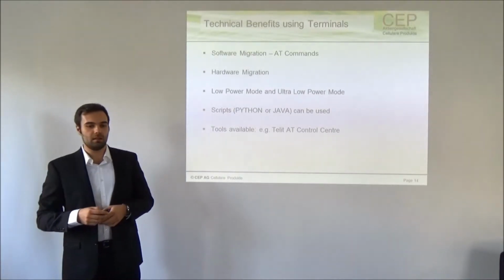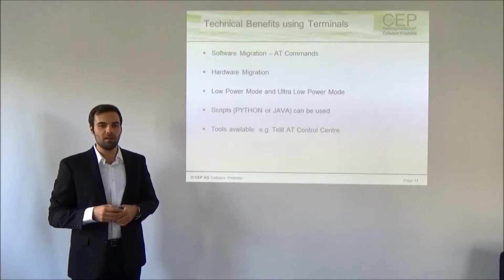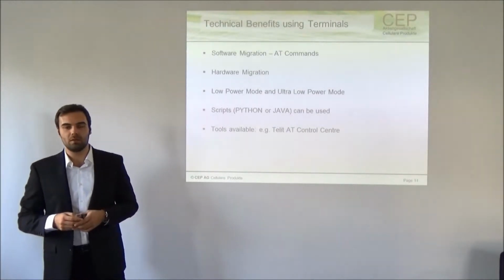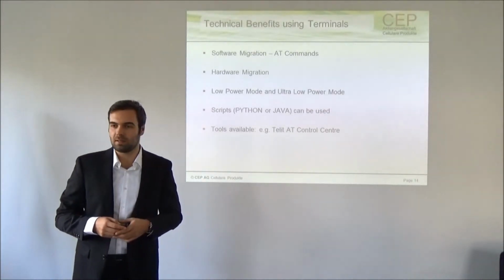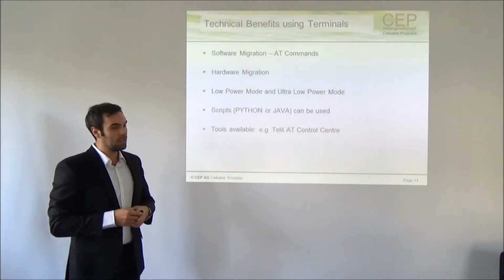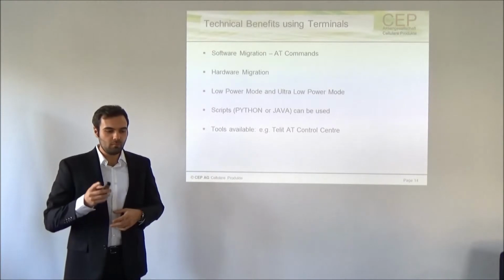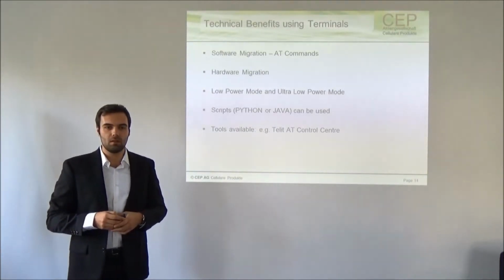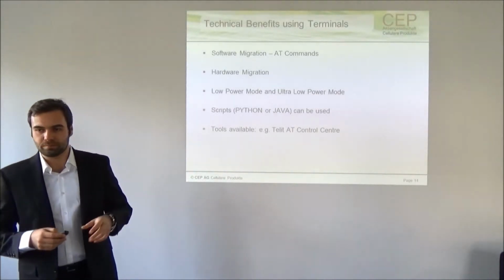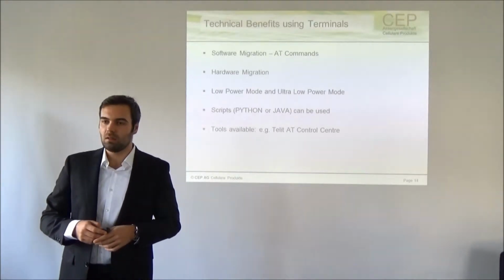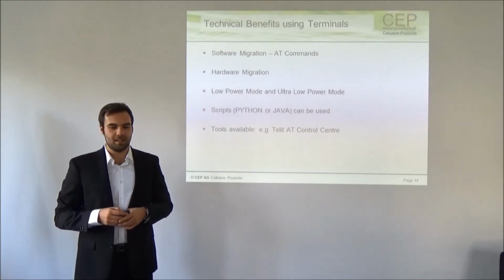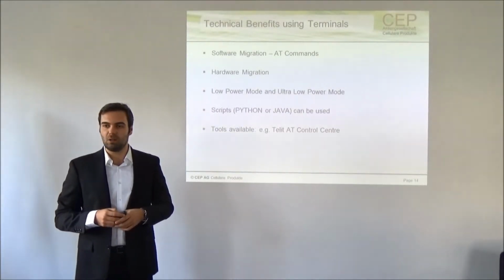Also we have low power and ultra low power modes on different terminals, so for some applications where we need a low power mode, that would be the right product for you. But I will say some more details about these special modes after. Then we have different scripts that could be used on terminals. We have two terminals that can be programmed with Python and Java. And there are tools available, basically from the module suppliers, to test the terminal, test the AT commands and so on.